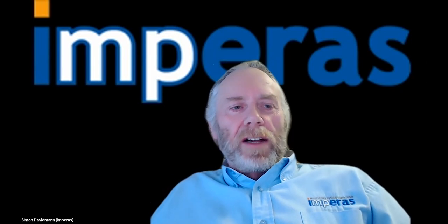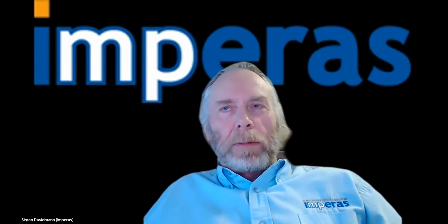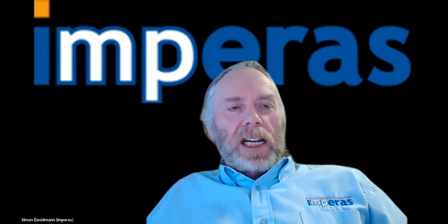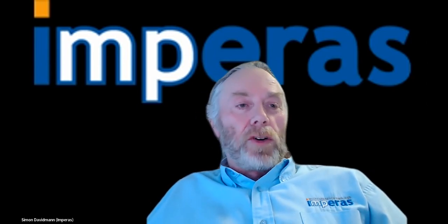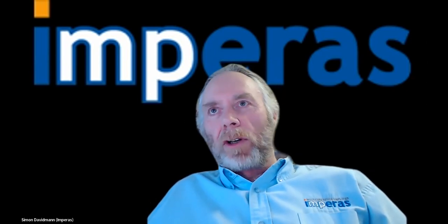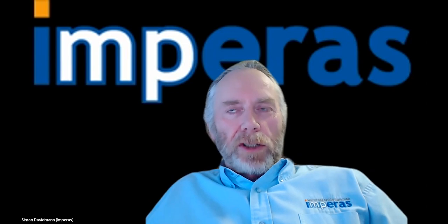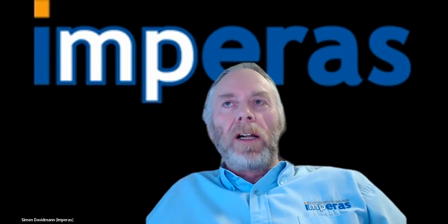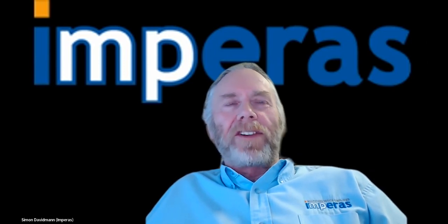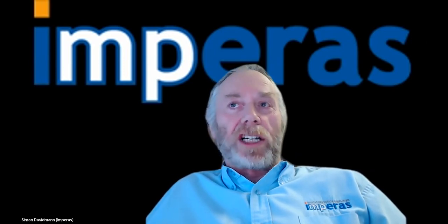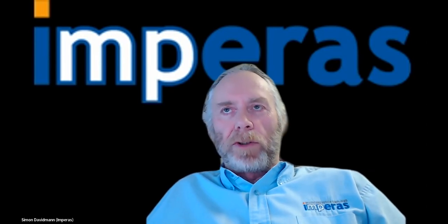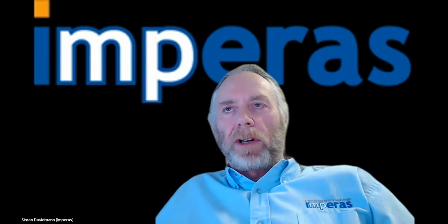What we've covered in this presentation is the different approaches people have taken. A synchronous approach is where, on instruction retire, you compare what's coming out of the RTL or DUT with a reference model. Yes, anybody can do that. The approach taken in open hardware uses an Imperas reference model. Everything but the Imperas reference simulator is open source; the Imperas reference simulator is not open source, so you have to come to Imperas for that.